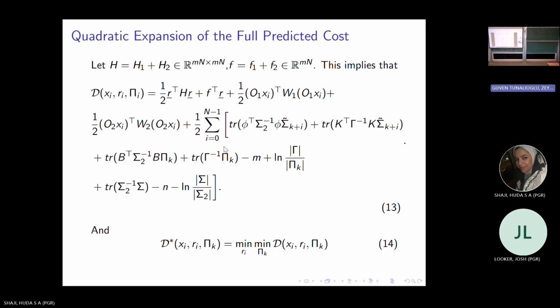Then we transfer the big function for Kullback-Leibler to this form. So we can see from here, we have this part that we worked on. This will be constant. This will be related to the covariances. Our aim is to do this optimization problem now. After doing model predictive control, we will do this optimization problem. We will get optimal R, optimal covariance. When we do that, we know that our actual controller is normal. If we know the mean and covariance, we can write our controller.